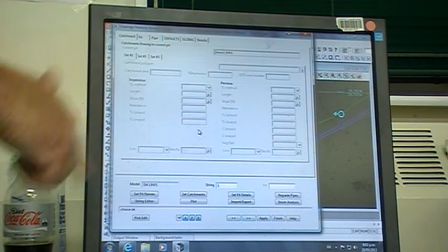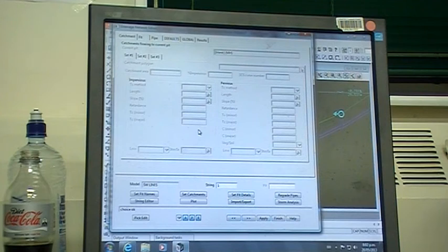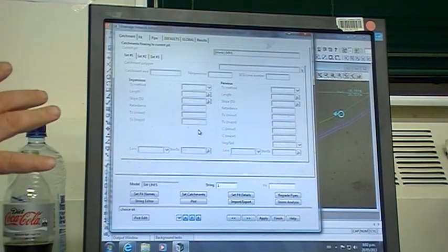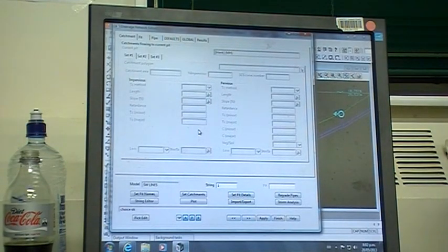The latest versions of 12D have got a thing called Tough Flow from Australia, which will calculate or make it more automated, and it also gives you minimum velocities for cleaning and all that kind of stuff, which is what council's normally concerned with. But as far as stormwater goes, most of the time we just stick to the default.